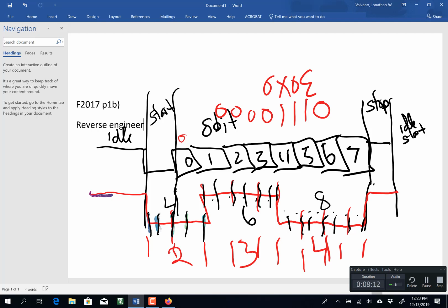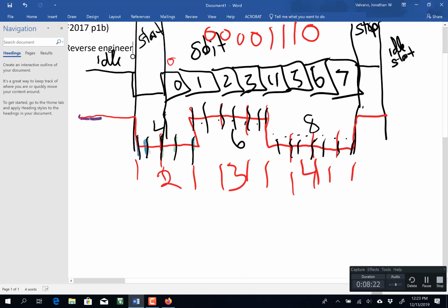Yeah, question. Is that enough? Is that what you wanted? So the thing that I do is I look for the least common multiple, and that gives me the bit time. I figure out the bit time, and then I draw my vertical lines such that I don't have a bit flipping in the middle of a bit time. It has to be low or high during the entire bit time. And then the baud rates went over that. Yeah, question? What would your max bandwidth be?